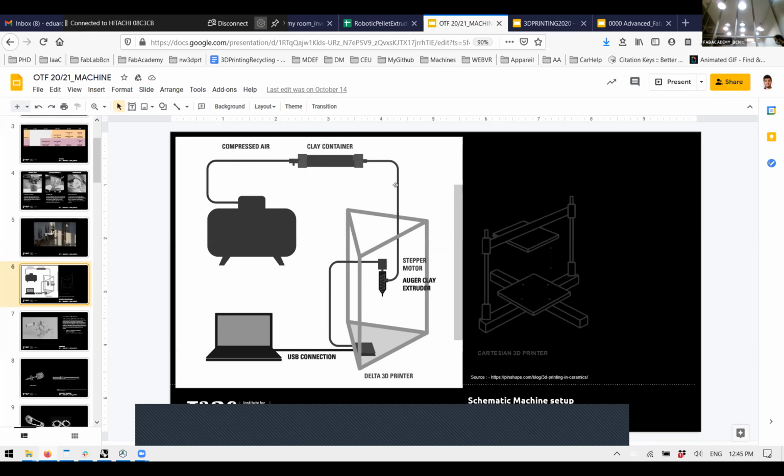What happens is that every time you finish, you need to take out the motor, clean the screw, and be careful that the clay doesn't get in the motor. The guys at the OTF who print the whole thing, each group has at least destroyed 3 motors and about 6 of these, just because they need to clean and take it apart, and they do it every day. This is an in-house design, and we just produce it here, we just print it. This is good, and you get really good quality.